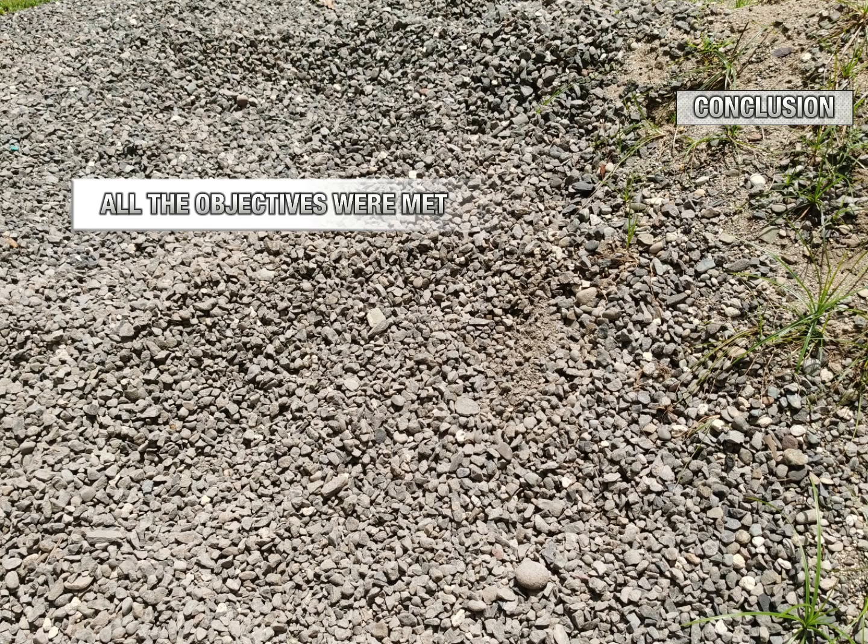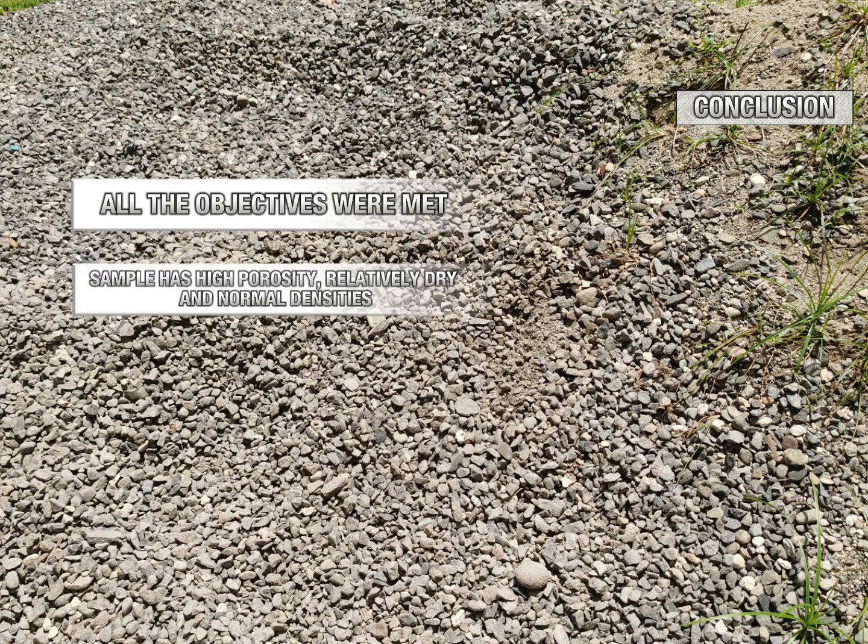The results of the coarse aggregate sample mechanical properties analysis indicate that the sample has a high porosity. We can assume that our sample is relatively dry and has a normal average density of 1,479.61 kilograms per cubic meter and a bulk average density of 1,750 kilograms per cubic meter that meet the bulk density standard of aggregates.